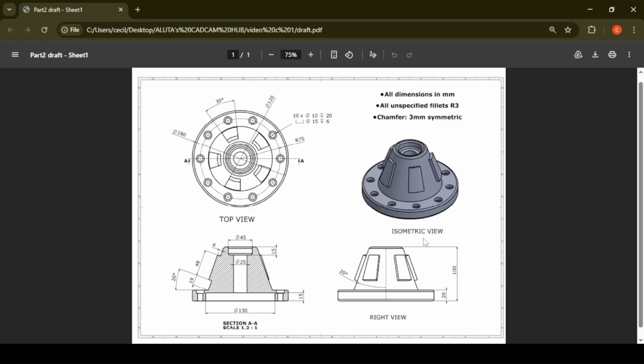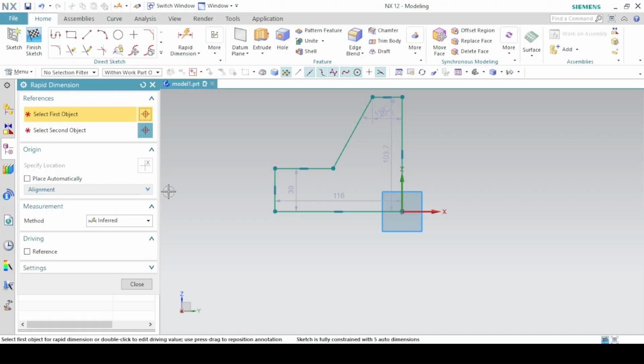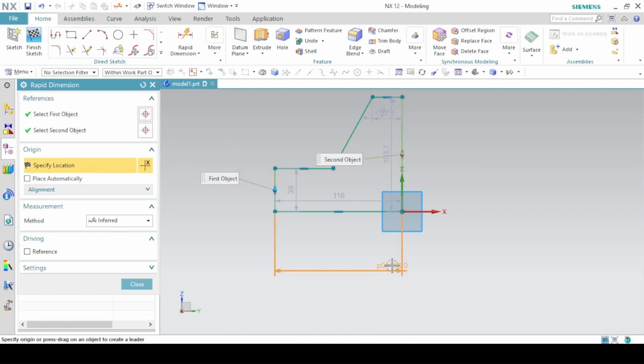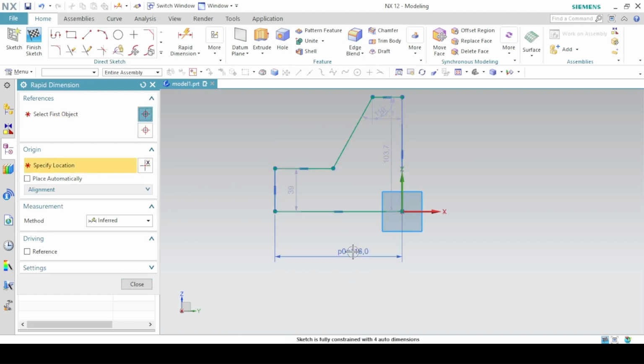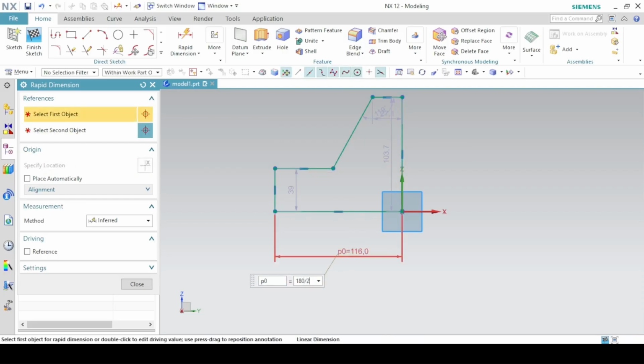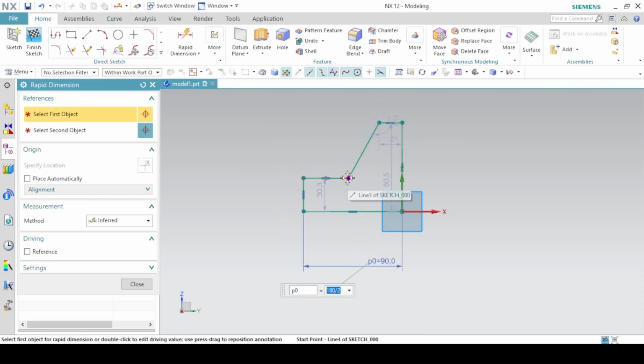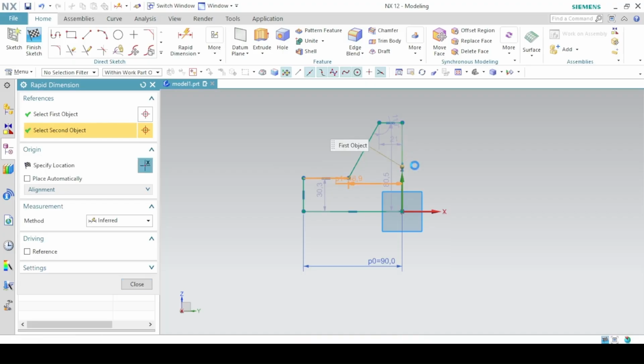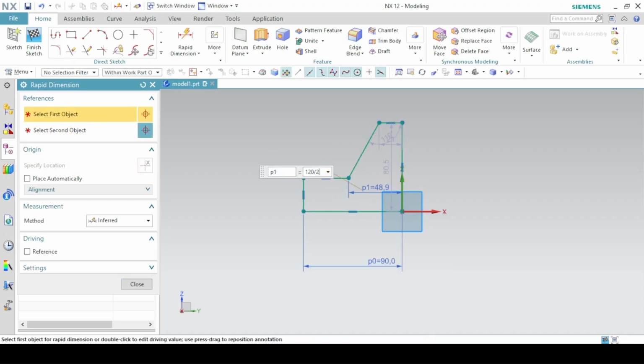And then the diameter of the base of the cone is 120 millimeters. So from this line to this line, since we sketched just half, it will be 180 divided by 2. And from the base of this cone to this center line, since we sketched half, that will be 120 divided by 2.